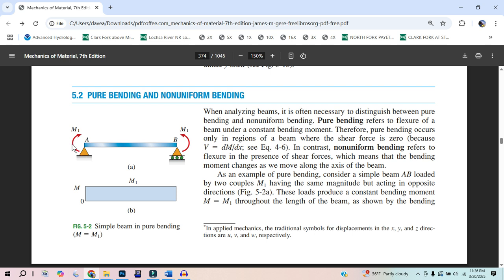And that would cause this to rotate that way, and that would be similar to this moment. And the other direction I could do it is a downward force right here, and then an upward force right there. Just get them fairly close together, and that would simulate as close as possible a pure moment. But I just wanted to bring in that scenario because you will generate no shear forces if you do that from the outside or inside of the applied loads. So again, if I apply a load there and there, the shear forces will be zero all through here, and you'll just have the resultant moment. So that's going to be what this second sentence is.